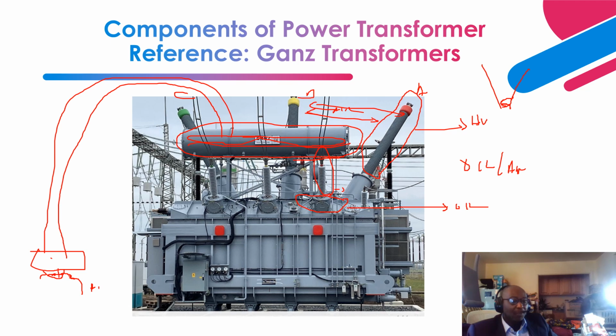As the air goes through the beads, it removes the moisture when the transformer is breathing in air, when it contracts during the cold season. So the air that is coming in is dry before it comes into contact with the oil. The goal is to protect the oil from the oxidative elements of the weather.